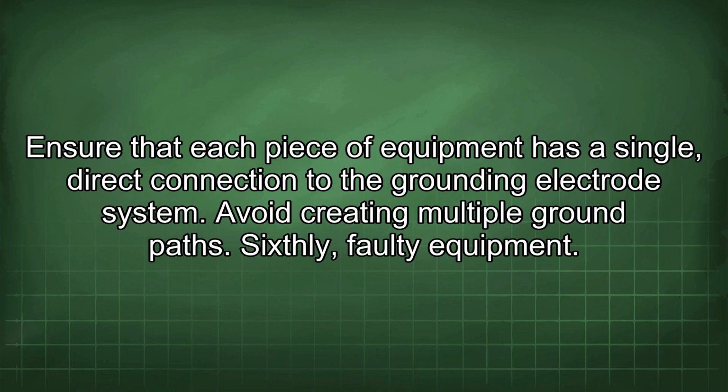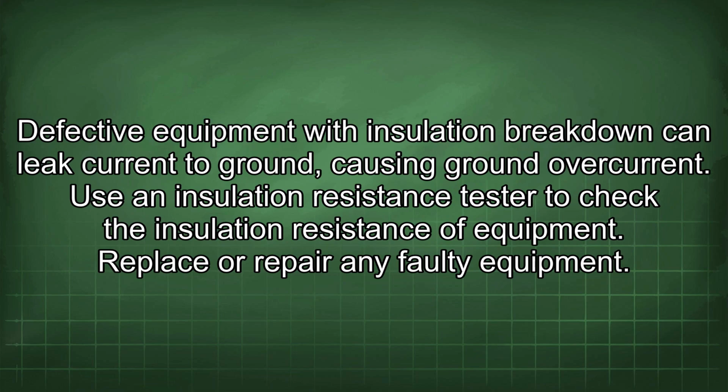Sixthly, faulty equipment. Defective equipment with insulation breakdown can leak current to ground, causing ground overcurrent. Use an insulation resistance tester to check the insulation resistance of equipment. Replace or repair any faulty equipment.